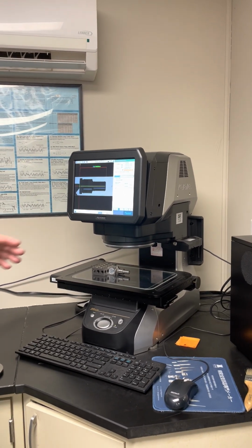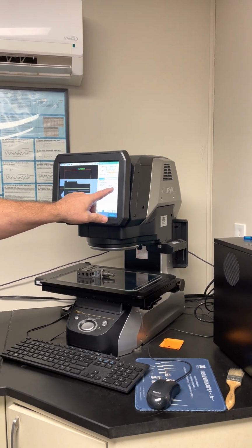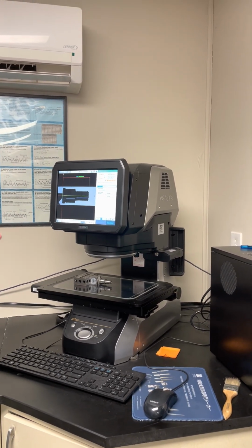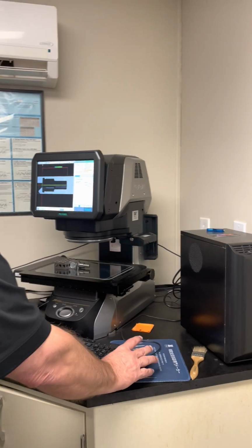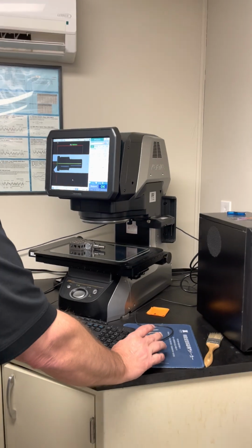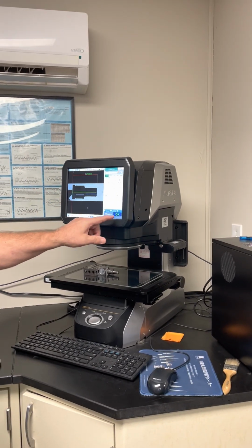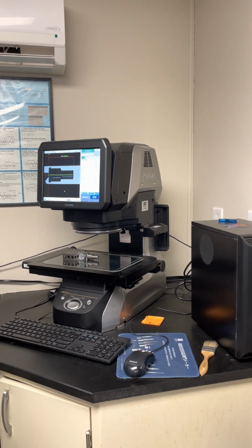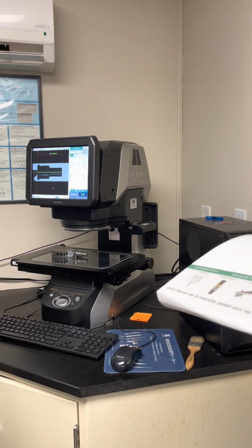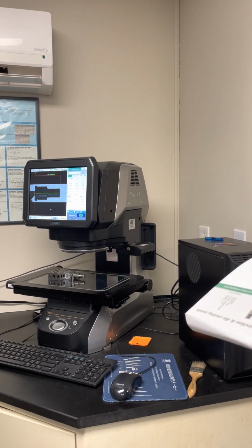And the reason I put the lower limit in first was because if I put the upper limit in first, it wouldn't let me, as you discovered the other day. So hit apply, and there we go. Now something else you could do is put a lot of the values in and then go to list edit, where you can copy and paste a lot of things.